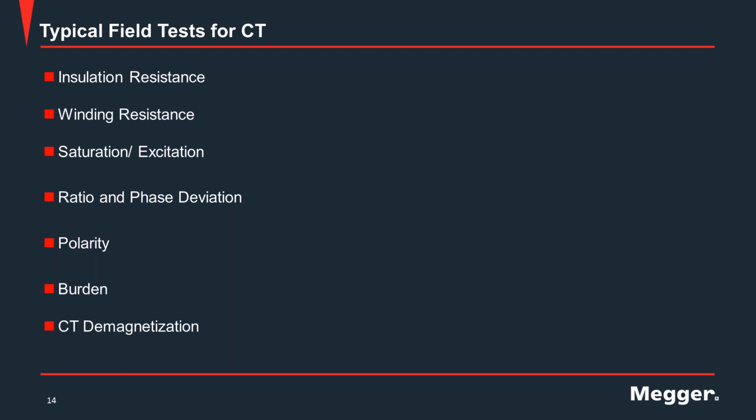Actually, the CT demagnetization is not a test, but a good tool or procedure to do in order for us to get better and more reliable test results. In some other cases, some customers also test the insulation power factor of the CT.